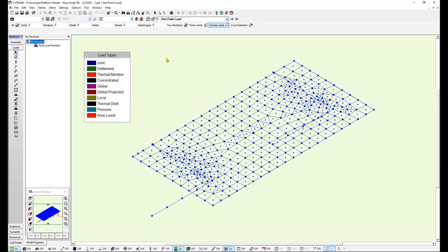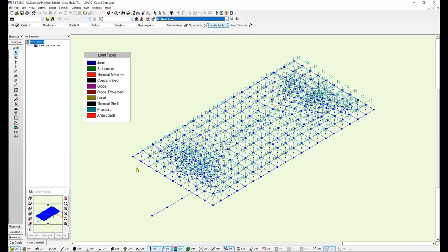And if I go to the loads window, in this case, I've defined a fourth load case called distributed load. So if you remember, I have these three previous load cases defined. So let's just display those loads. 200 kilonewtons at the top of each beam. The vertical, the horizontal, I just have 5 kilonewtons in the x direction. The self-weight of the structure, and the distributed load, which I have applied as a pressure load. So each shell has a value of 15 kilonewtons per meter square.